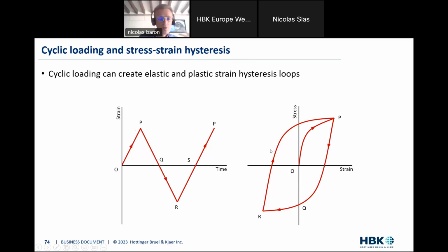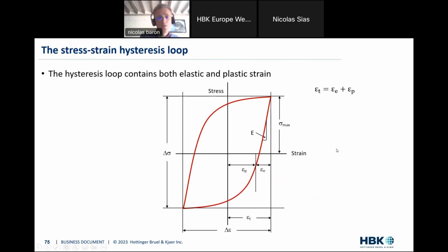So you load and you drive and you measure the strain values, and you depict the curve, the relationship between stress and strain, in this form. And that's the reason why the strain-life methodology is much more complete than the stress methodology. It is more complete because of the plasticity part, the one you see here, the small epsilon. Epsilon stands for deformation. This plastic deformation is there on the stress-strain curve. So not only do you have the elastic deformation that you have with the stress approach, but you also have, in addition, the plasticity value here.